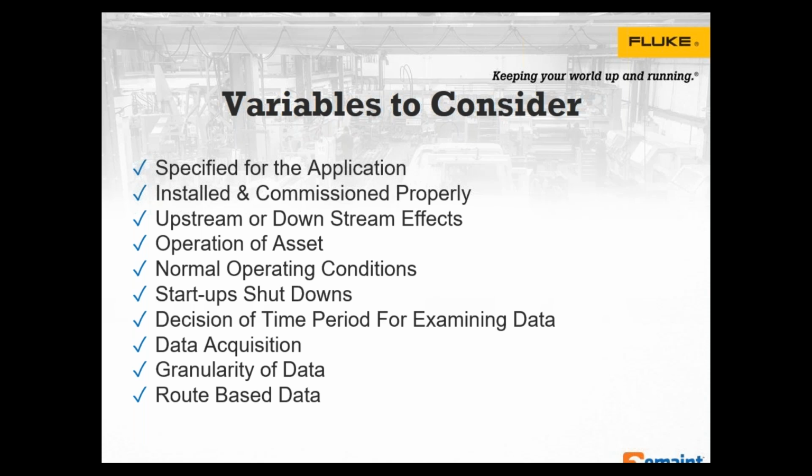What about what I'm calling route-based data, where an operator or a maintenance tech goes out and takes a vibration reading with a vibration analyzer, and has to input this reading into a CMMS system? Those are things to consider. Is the operator actually going out there with pen and paper, writing this value down, or is it being captured in some digital fashion that can be transferred into the CMMS system?